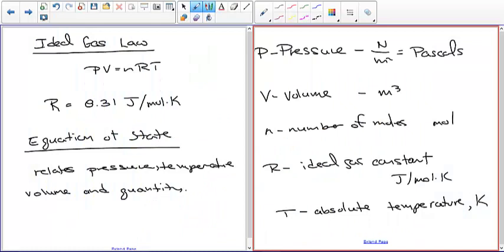But if you look at the flow of air around wings or the flow of air in jet engines, it behaves like an ideal gas. So you can use the ideal gas equation. My PhD thesis looked at transonic flow, meaning flow between supersonic and subsonic, and I used the ideal gas law to relate pressure, temperature, and density. And with that assumption, you can do a lot of interesting calculations with air.